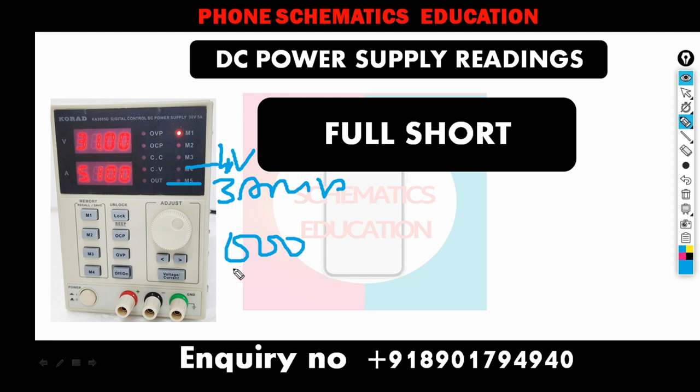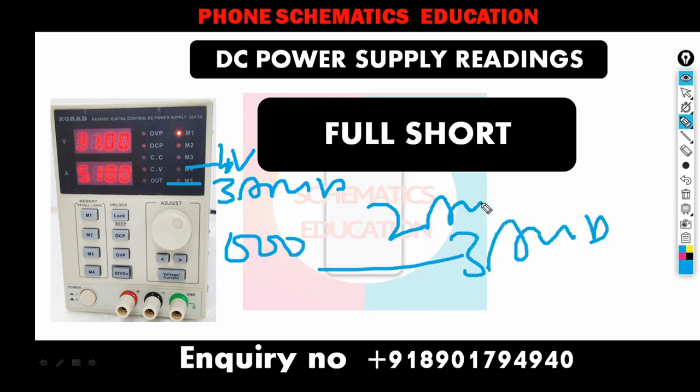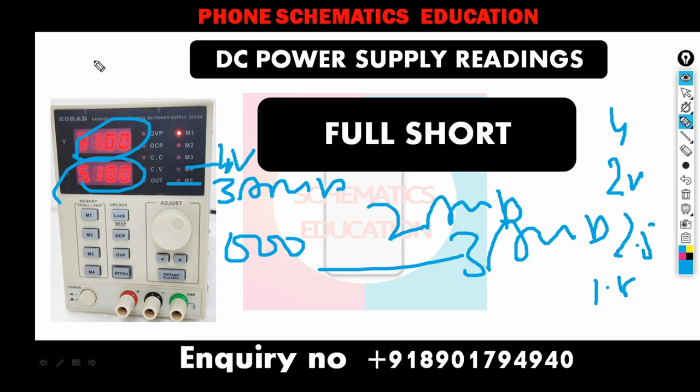After connecting, the current goes up to 3 amp, 2 amp, and the voltage also drops from 4 volt to 2 volt, or 2.5, or 1.8 volt. That means there is a short in the primary line. We can call it a full short. I hope you get my point.